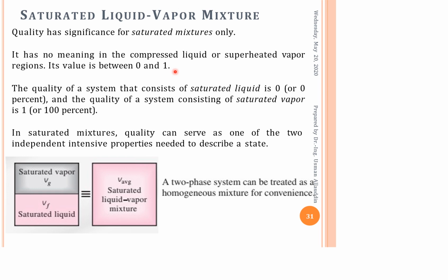So it explains how our liquid is converting into vapor form. 100% means that all the liquid is converted into vapor, and 70% or 0.7 means 70% of the liquid is converted into vapor. So now 30% is left, which is in liquid form, and 70% is in vapor form. That's why the value only matters for a saturated mixture, because it is constant for compressed liquid, which is 0, and 1 for the superheated vapor. It cannot be more than that, because 100% is the maximum limit.